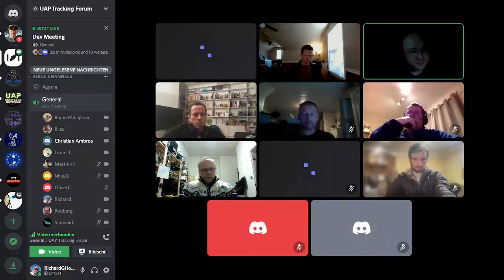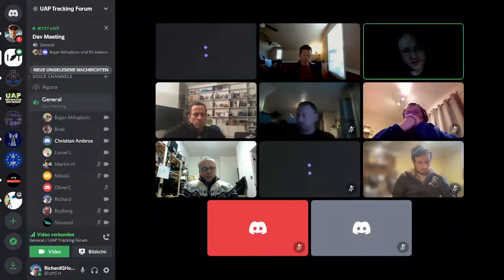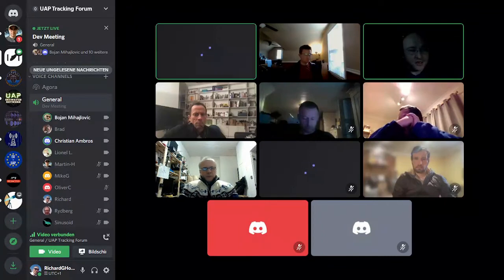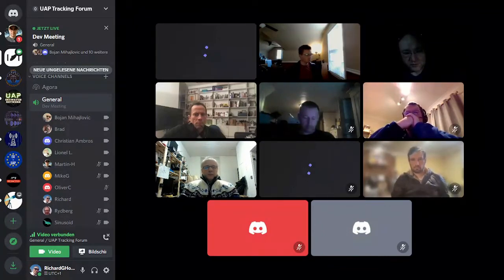The software stuff, TIS cams are provided with a disk image for the Nano. I couldn't get anything to run on that part, so I skipped it. And the last camera was the IMX 226 with 12 megapixels, and the frame rate was down to 1 frame per second. So the only camera that worked fine was the RZ120 Mini with a decent frame rate, but with Pergear lenses that require an APS-C sensor, we just have about 90 degrees of field of view. So if we don't find any suitable camera that goes with, let's say, a 1-inch chip, we have to look for other suppliers.